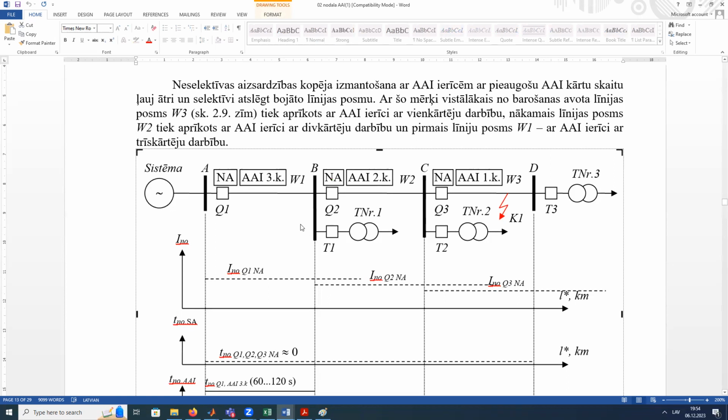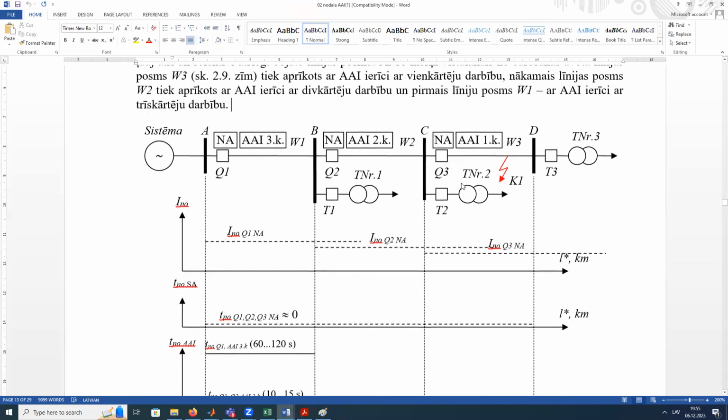So the idea is that every time we disconnected everything and tried to reclose everything while we have enough power for the recloser, mechanical power. So that's why there is the possibility of 3 times connection back, 2 times, 1 time. And this is then we are disconnecting, connecting back, disconnecting, connecting back. But due to this series of tries, we make this selective operation.